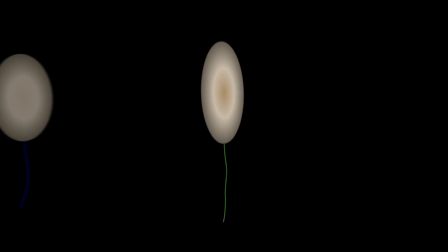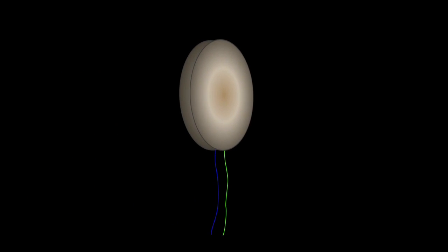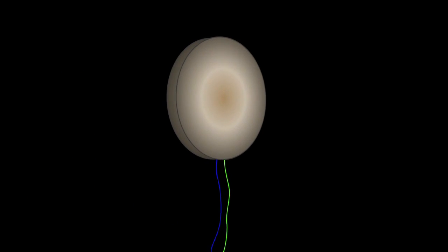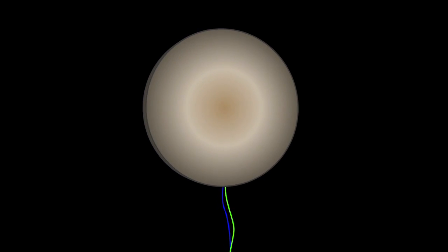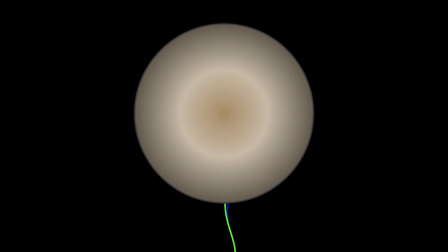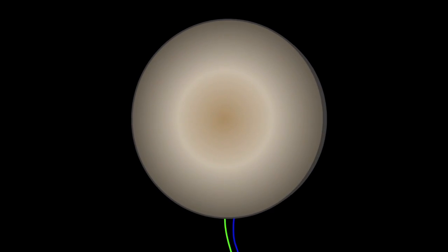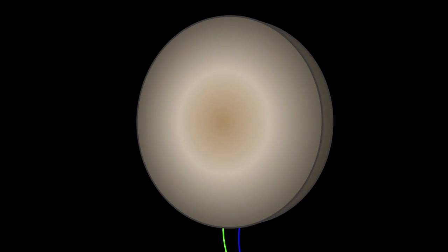A condenser microphone uses a thin conductive diaphragm held close to a disc called a backplate. This arrangement basically works like a capacitor. When sound pressure acts on the diaphragm, it vibrates slightly in response to the waveform. This causes the capacitance to vary, which causes a variance in the output voltage. This variation is the signal output of the microphone.